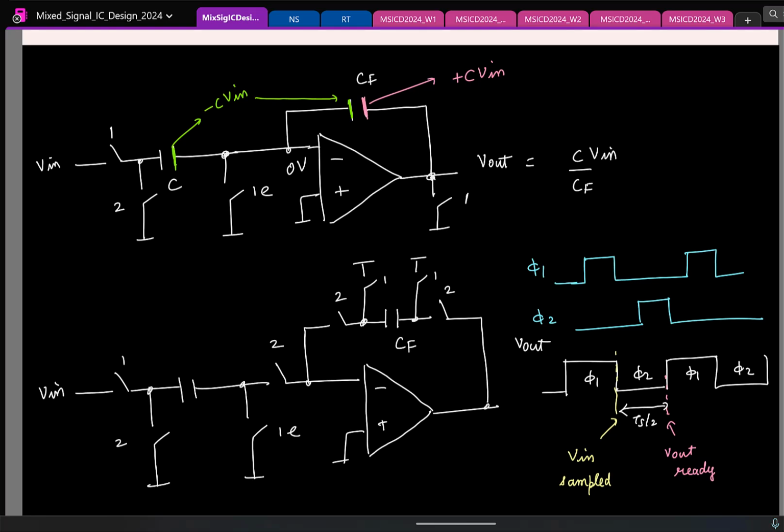So is there any significant delay between phi 1 and phi 1e? Not a lot. It's just a few hundreds of picoseconds of delay. Likely happens when phi 1e moves. Correct. Yeah, for this analysis we'll ignore phi 1, phi 1e. Again, the delay is usually a few hundreds of picoseconds. That's all. This is just for our bottom plate sampling. So again, we'll not consider these effects because it's fine.